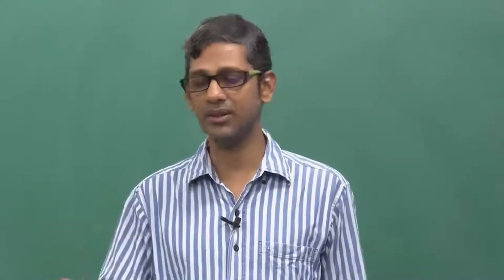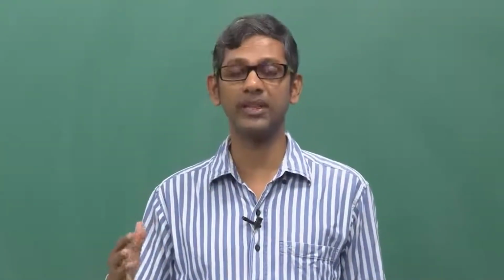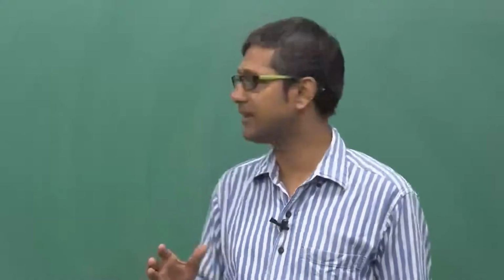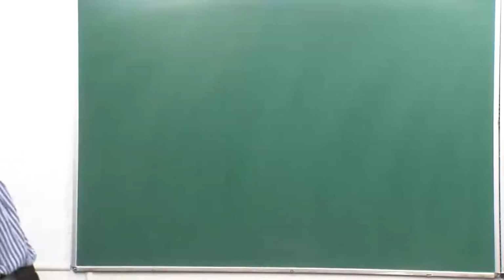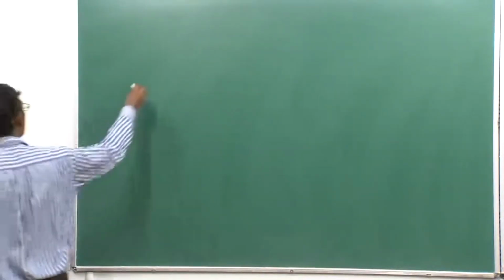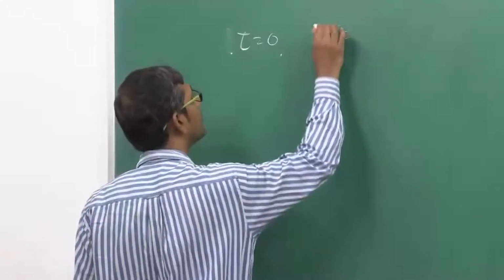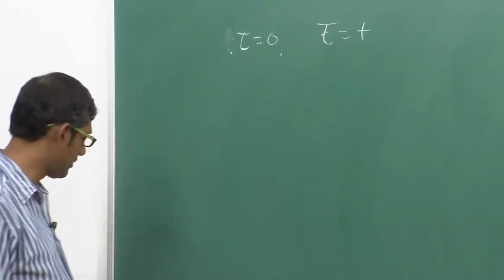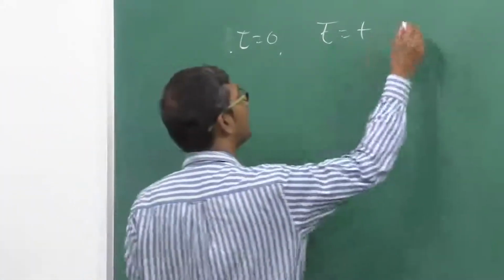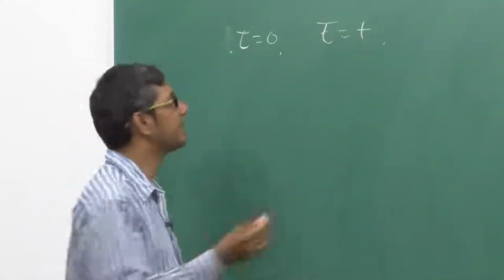In the recovery stage, these grains might have nucleated, just nucleation. And then subsequently, as you increase the temperature, the growth takes place. So, the predominant aspect is that growth happens from the beginning, from the time tau equal to 0 to the time tau equal to t. That means from the beginning itself growth happens, and such a situation is very simple. We also assume that after the growth started, there is no further nucleation.